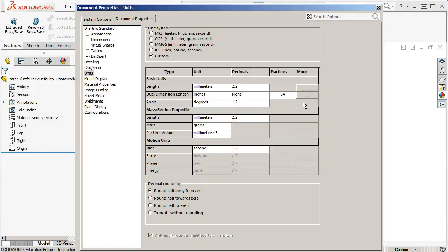And then what my argument always was, with your 16ths ruler, you should be able to see halfway. So is it closer to this number or closer to this number if it's in between, not just it's a 16th. So I would typically go to 32nds, which drove a lot of people crazy. So take your pick. And then the other thing is round to nearest fraction. If you don't round, it will instantly revert back to the decimal. It won't say this is a 32nd up or a 32nd down. All right, so instead of decimal, I can set fractional.